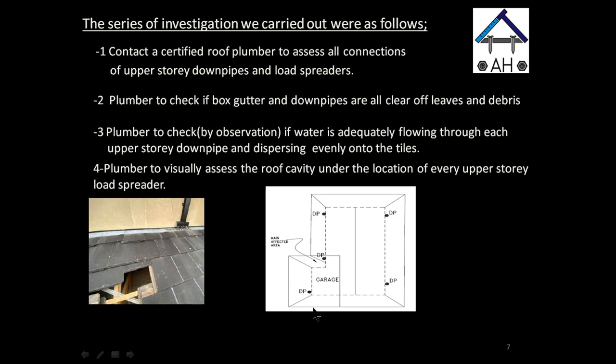We did not only assess the leak in the garage, but have also suspected that water could be seeping into the roof cavity under other wrongly installed spreaders as well. Although the clients may not be aware of any problems as yet, it is possible that water could be trapped in other locations within that lower roof cavity. It is only a matter of time before sealing failure would occur the same way as we saw in the